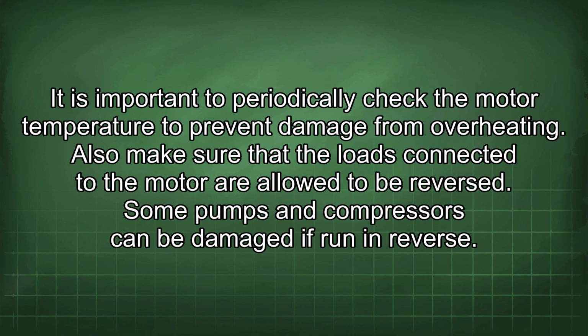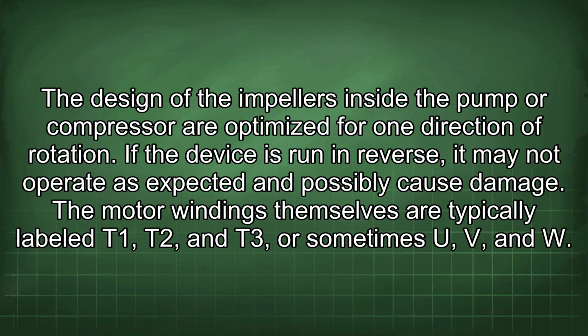Also make sure that the loads connected to the motor are allowed to be reversed. Some pumps and compressors can be damaged if run in reverse. The design of the impellers inside the pump or compressor are optimized for one direction of rotation. If the device is run in reverse, it may not operate as expected and possibly cause damage.